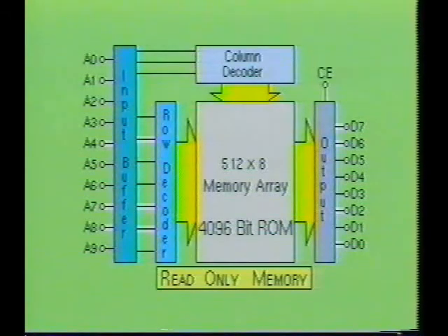Then the chip enable input is brought high, which causes the data stored at the specified address to be output via the IC's output pins, which are labeled D0 through D7. The data then travels along the data bus to the microprocessor. Typical access time for such read operations is approximately 15 to 80 nanoseconds for most TTL ROM devices.